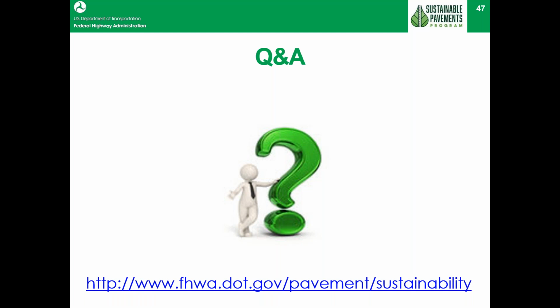I believe so. I think it considers the pavement design. So if you have, instead of an 8-inch base and then 4-inch overlay or asphalt thickness, something like Tensar or whatever as part of your base stabilization, I think you would look at the different aggregate production, and then also what's the production for that mechanical stabilization tool that you're using. So that's where you would have to compare the different pavement designs that you can use.